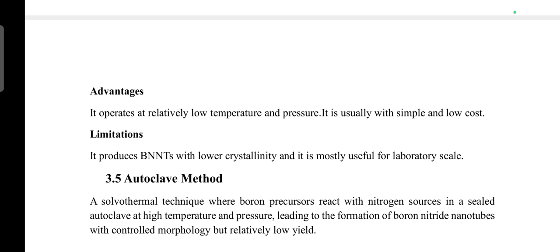We can say that it is a technique in which the precursors react with nitrogen sources in a completely sealed autoclave or machine, in which a high temperature and pressure is maintained for the formation of boron nitride nanotubes, and all the conditions should be controlled.